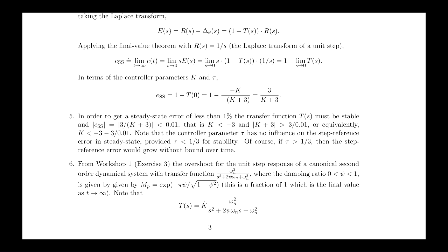It's a disturbance. Well, it's not noise necessarily, but the input to the plant is the voltage, so it's something that's disturbing the voltage somehow. If I push the top, that will cause some motion that will change the back EMF, which is like a disturbance on the voltage. It can represent me pushing it by virtue of the internal feedback that converts motion, or rate of change of position, into a change in the back EMF. But it's not direct.